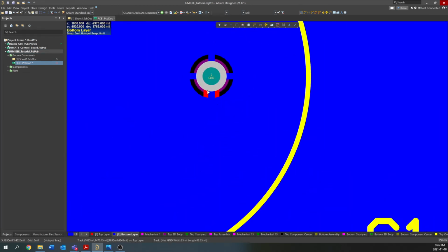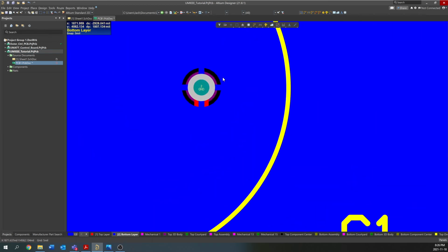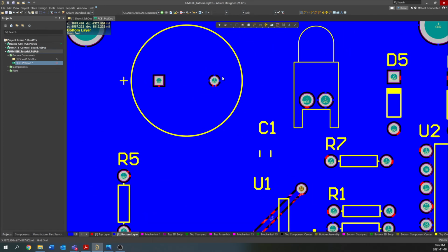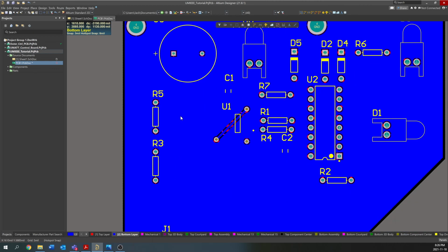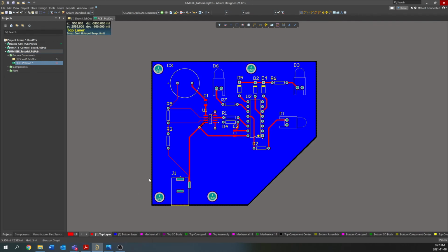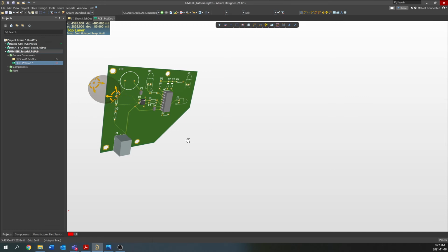And you can actually specify how Altium connects to their nets. You can either go all the way around, it can just be the net, the one ground via here, or through hole can be just one with the bottom pour, or you can have different connection setups. Whatever you want, and that's specified in the design rules. So there you go. That is essentially the finished board, and we can see it in 3D here. Nice view of it. It would be cool if we had the LEDs, but we don't. And you can actually see here on the bottom.